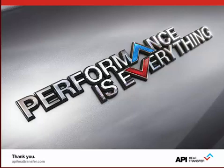Yeah, generally a plate heat exchanger is looked at as a pressure vessel. So the typical pressure vessel code applies for plate heat exchangers. Even though there are some exceptions, for example in China, because there it is not 100% regarded as a complete pressure vessel. But in the Western countries, Europe, it's completely looked at as a pressure vessel. So the code is ASME, PED in Europe, CRN, and all the local codes.